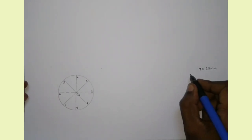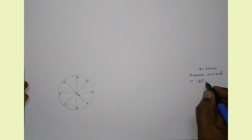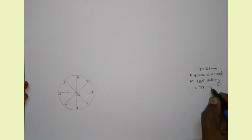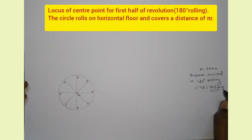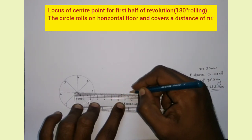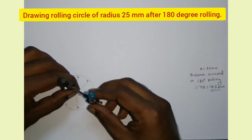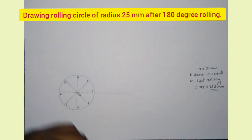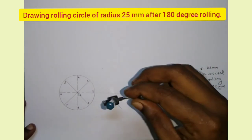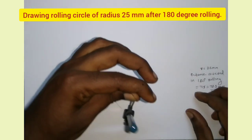So the distance covered for 180 degrees of rolling, that is the first half of the revolution, is pi r, that is 78.5 mm. So now I am drawing the locus of the center point for the first half of the revolution, that is rolling on the horizontal floor. Okay, now I am measuring the radius 25 mm and I am drawing the position of the rolling circle after 180 degrees of rolling.